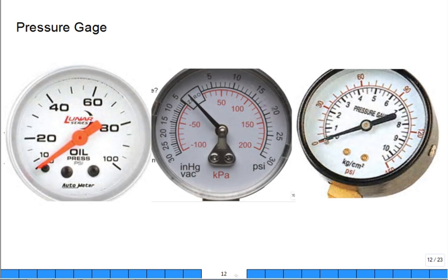Here's some other gauges just to show you. What is this one? This one's actually made to measure oil. It looks like it's good to measure between 20 to 80. Leave the ends alone. You know, typically the first 5% and the last 5% are not good on a gauge to be accurate. But here's another one.